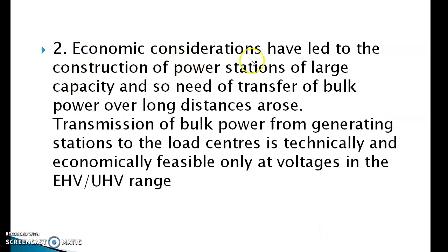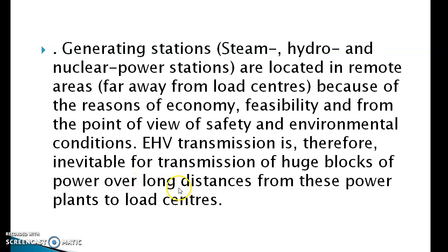Second, economic considerations have led to construction of power stations of large capacity, and so the need to transfer bulk power over long distances arose. The transmission of bulk power from generating stations to the load centers is technically and economically feasible only at voltages in the EHV and UHV range.